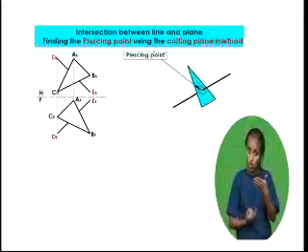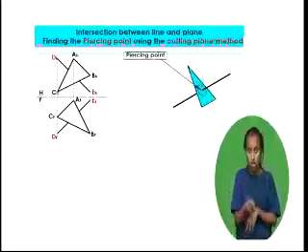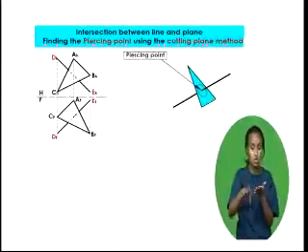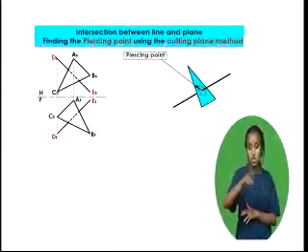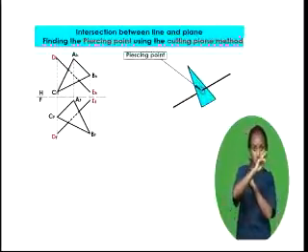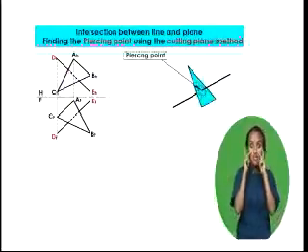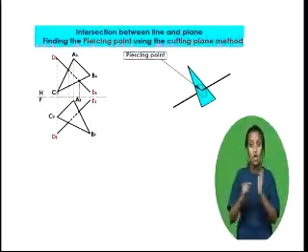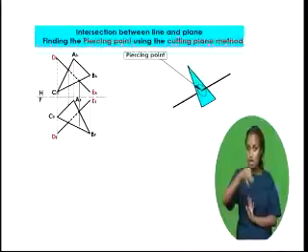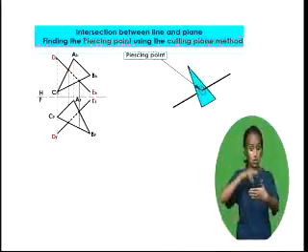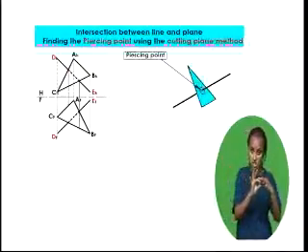Draw the horizontal view of the projecting plane through RH SH to establish DH EH as shown in the horizontal view in C. Locate DF, EF and draw the frontal view of the line of intersection.